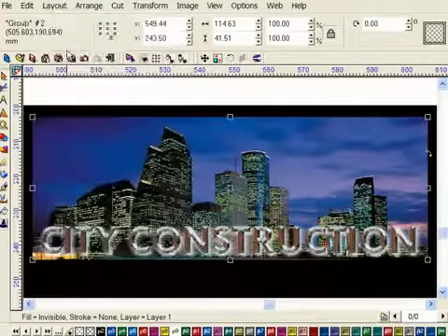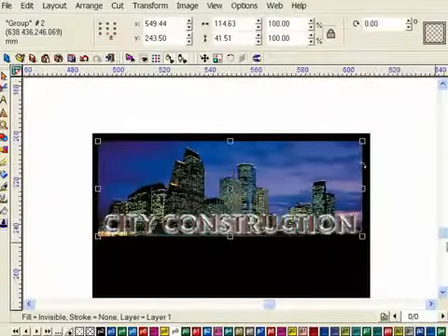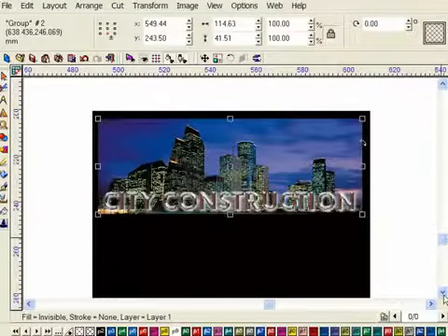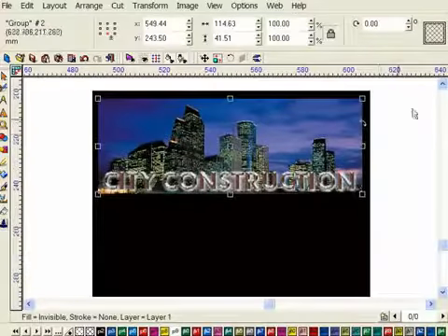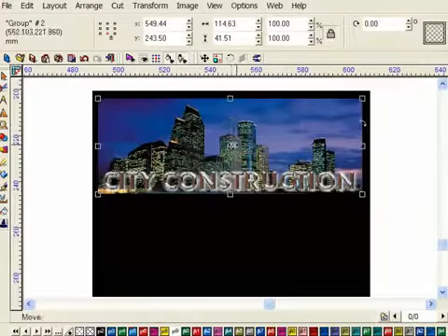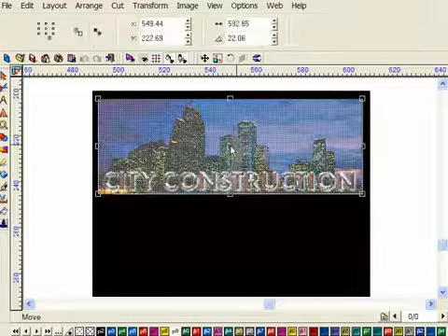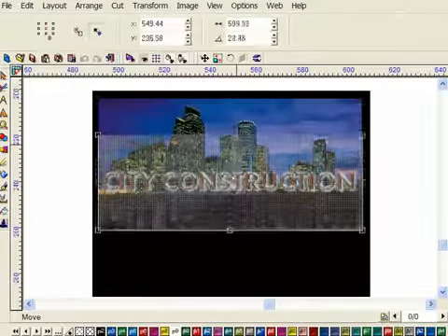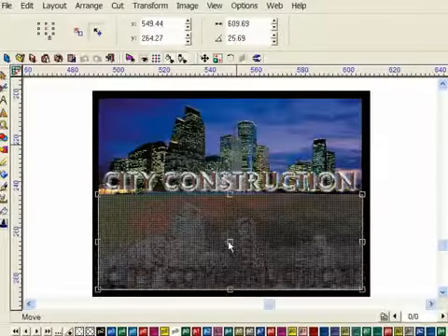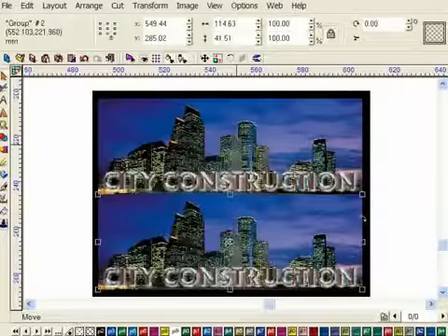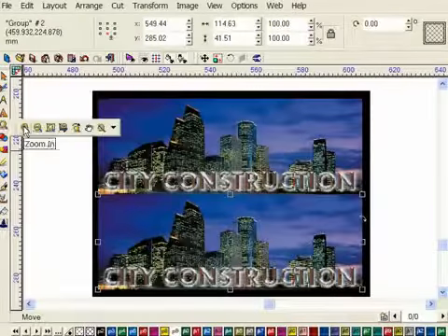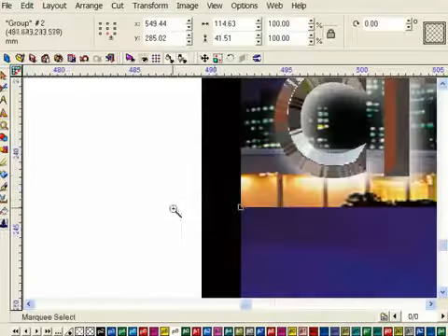There are several ways that this can be done in Synapse, and one way I like to use is to press and hold the Control and Alt keys together on the keyboard. Then, whilst keeping them held down, click on the middle nub of the selected object and move it down the page until you reach the desired position. This will do two things. First and most obvious, it will create a copy of the selected images, but secondly, it will constrain any movement of those images to the same axis, so the image below is perfectly in line with that above.